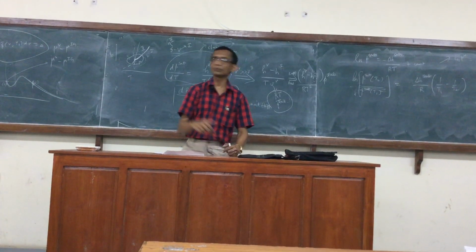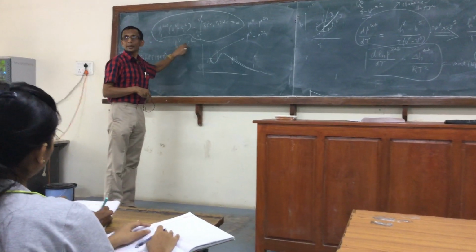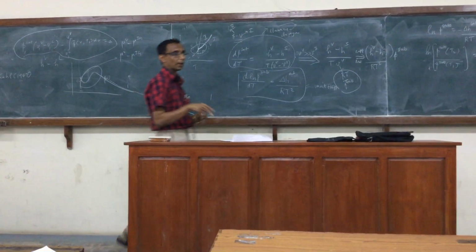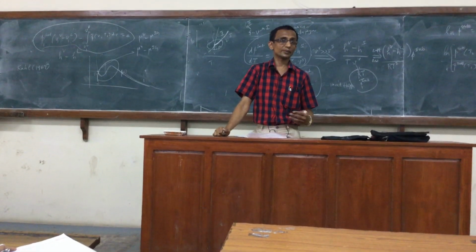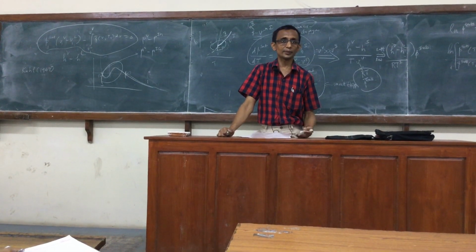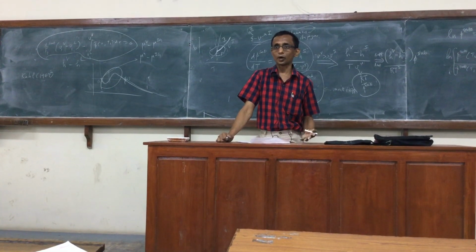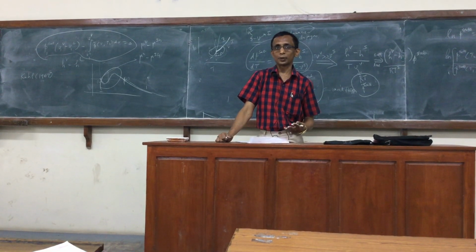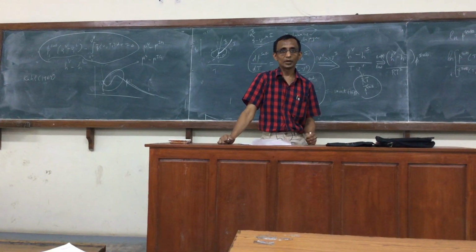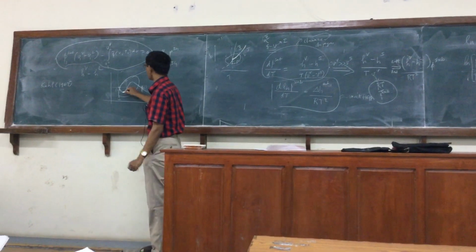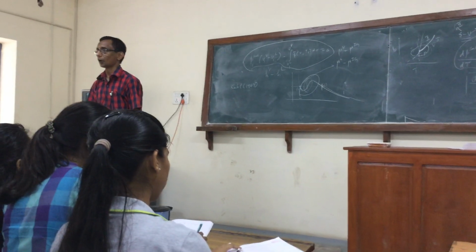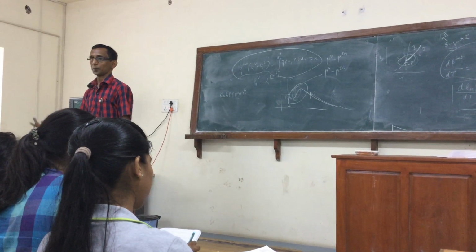So this is where the problem is, that what has been pointed out by many people is that we are able to avoid giving any energy input because this integration will induce integration over an unstable part of the isotherm, which doesn't physically exist or doesn't represent anything physically, which cannot be measured at all, right? That is the fundamental problem, that we are doing that, and in the process we are violating a fundamental rule. The thermodynamic properties are really not defined over this, but we do get something that we are able to avoid having to give any input in terms of specific keys and so on.